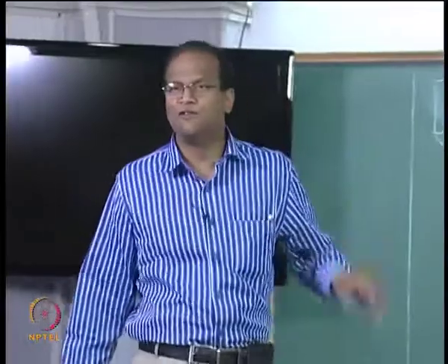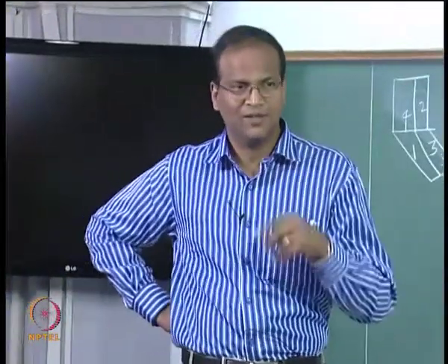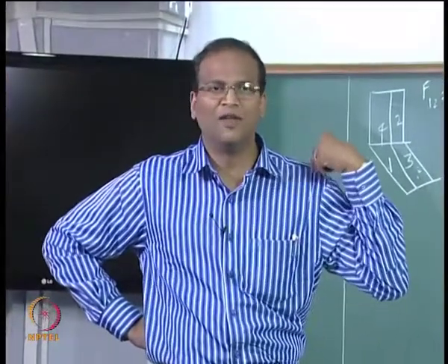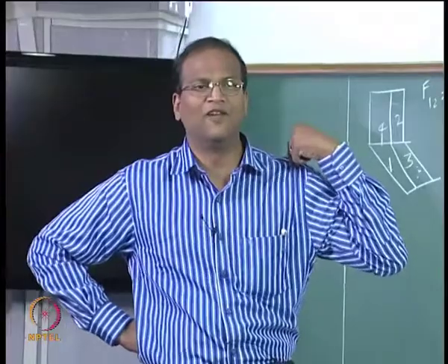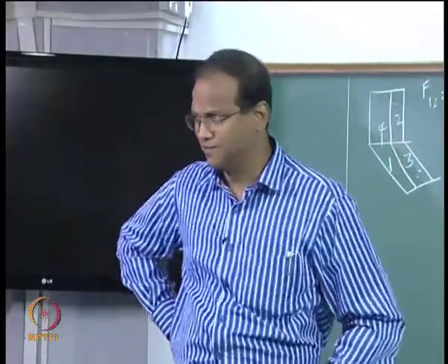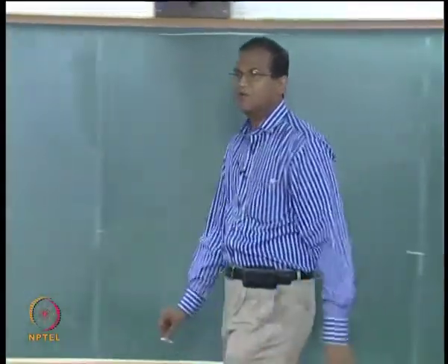Now of course your Fluent software can handle all this. You can divide it and it will get the view factors, it will do the contour integration and get the view factors. But still, if you have n number of surfaces where n is only 3, 4 or 5, you can still do these hand calculations. Is this clear?